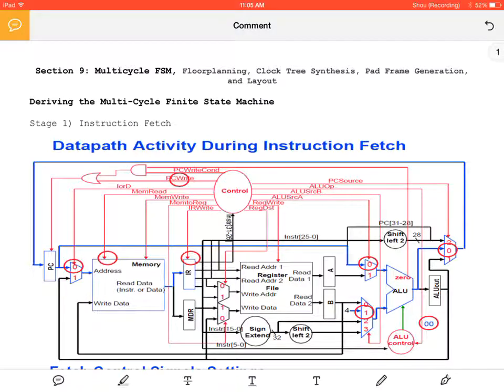In this case, an add-I is what happens if you have, let's say, C code J equals A plus 5. You're going to have the binary value of 5 physically in the instruction. You're going to sign extend it to 32 bits, and then you are going to actually add it in the ALU and store it in the register. So you can't use the R-type finite state machine states because it's actually taking a different set of inputs. So you have to make one stage modified, and I'll show you how to do that today.